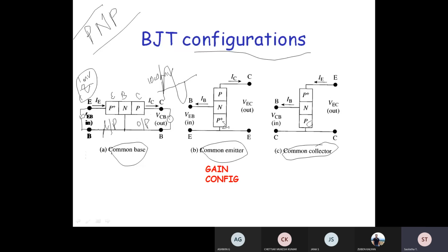Input voltages are connected across emitter and base. This particular signal is given with the help of the function generator which is available in our lab. That may be connected between emitter and base, and the property of the transistor is that it is used to amplify the signal because of the current flow, which I will explain right now. I can take the output with the help of one CRO. CRO means cathode ray oscilloscope. It's a device which is available in our lab. With the support of a CRO or voltmeter, whatever it may be, you can take the output.